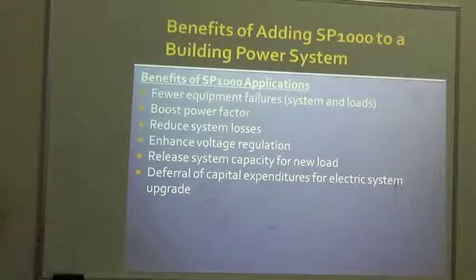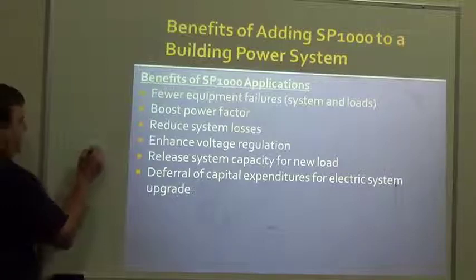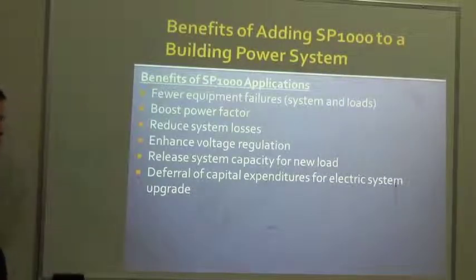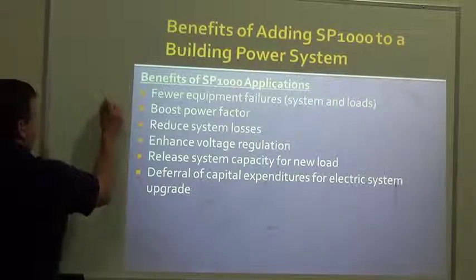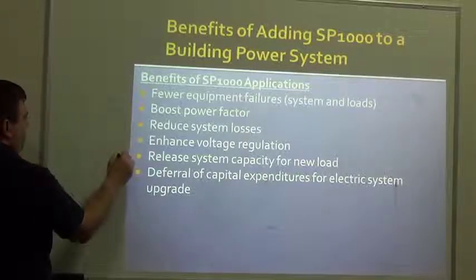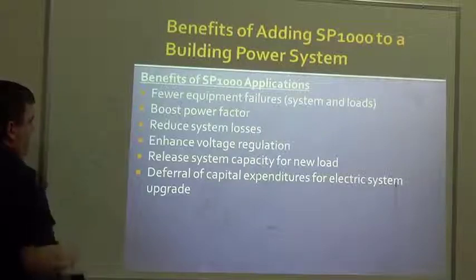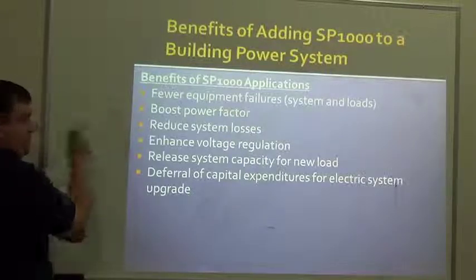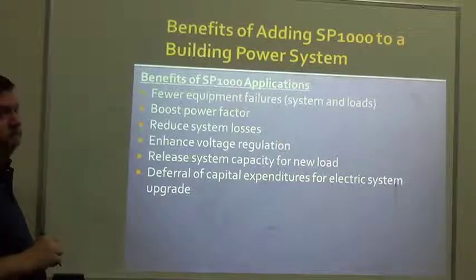Well, some of them, but anyway, this creates the harmonics, the reactive power that has to come this way. You don't want to go to the solar manufacturers and tell them they've got to change, and I don't think that's what you're saying, because they're going to say that's going to make our system look bad. So it's the customer. If you have a customer that has a high reactive power situation and is going to implement solar, that's a customer you definitely want to target.